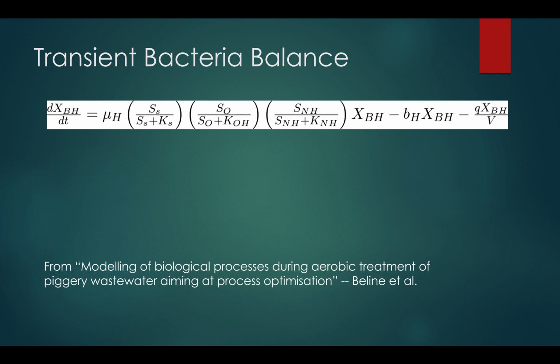Here we have our transient bacteria balance, which balances the mass of bacteria in our tank. We got these equations from the article below, and we're going to step through the important parts of it real quick. First we have here XBH, which is the mass of bacteria, and we're going to be modeling how that changes with time.